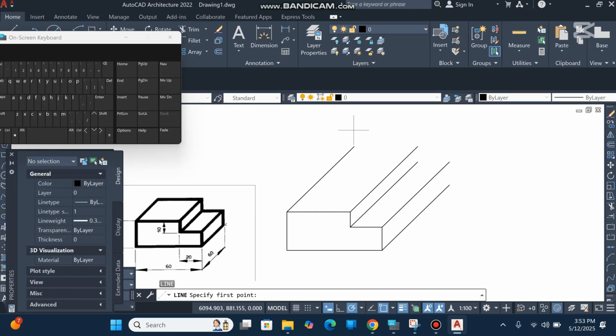L, enter. If I select this point and I'm going here, if you realize it says 0 degrees at 40, so the length of the line is 40 millimeters, but the degree is 0. Why? Because it is a straight line. So we're just going to select that. Now we're going to go down to the next point. Realize it is at a 90 degree. So vertical lines and horizontal lines only are supposed to be used to connect your points.